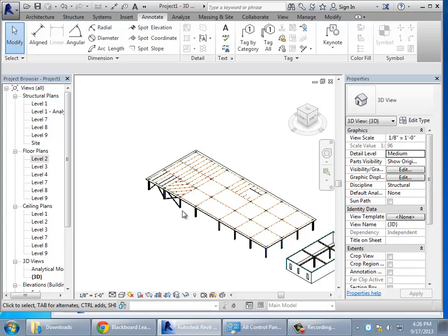Not only will it save you the work, it'll also make sure that there's consistency and everything's lined up perfectly. If you're trying to line things up and just draw my level on top of your level, it's so easy to get a half inch off or a quarter inch off, and it just doesn't quite connect the way you want it to be. Copying and pasting so that it's using the same XY coordinates will just guarantee accuracy. So you want to think about doing that.